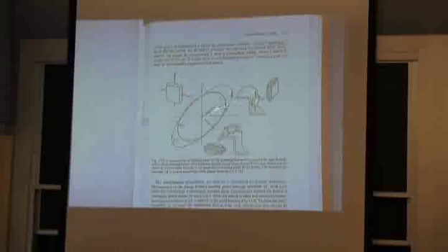If it were isotropic, it would be exactly half. If it's anisotropic and I have an R value greater than 1, it's actually going to be a biaxial tension that's greater than half of the downward tension. Okay? But in any case, it's biaxial loading with unequal tension, and I just use the construction.